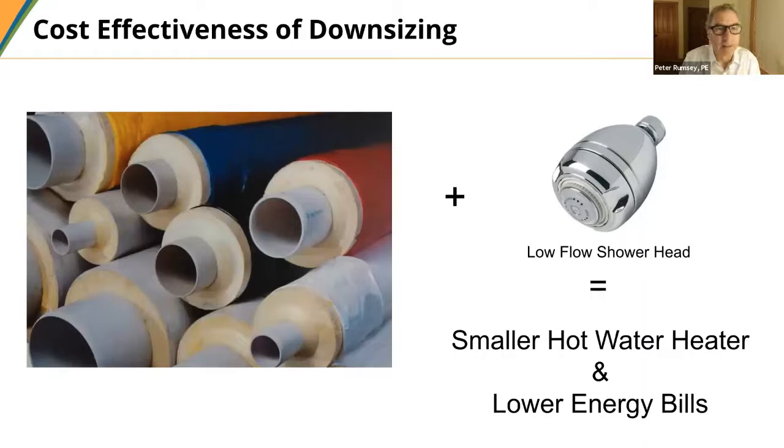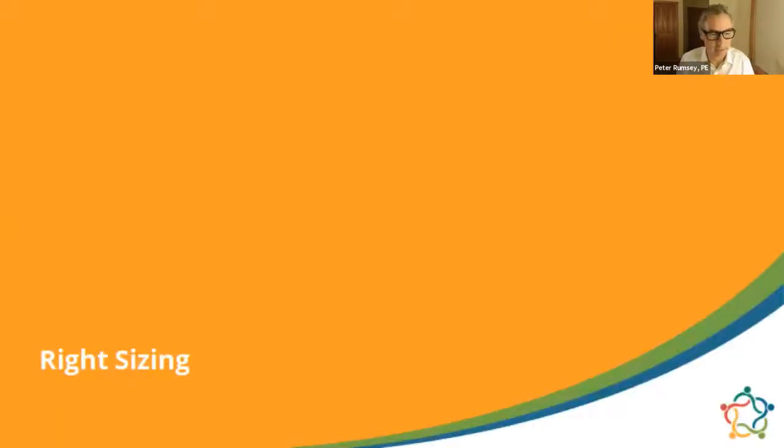You are on teams together, so the engineer can say, can you please put a little bit more insulation in the wall so that my cooling system goes down one size? And then that going down in size of the cooling system helps to pay for the insulation, right? So this is a key and very fundamental, important idea about load calculations.